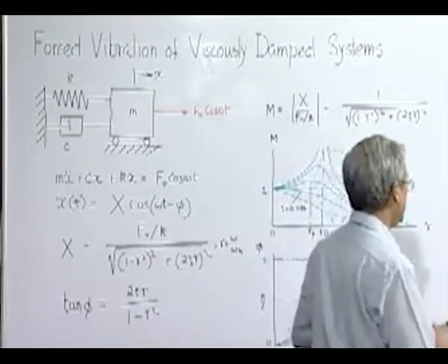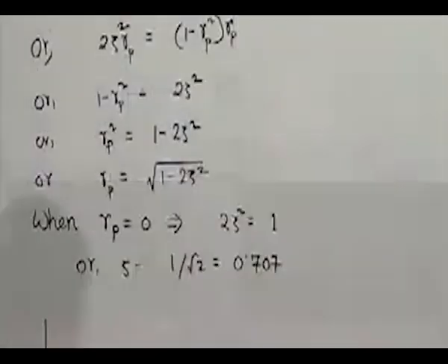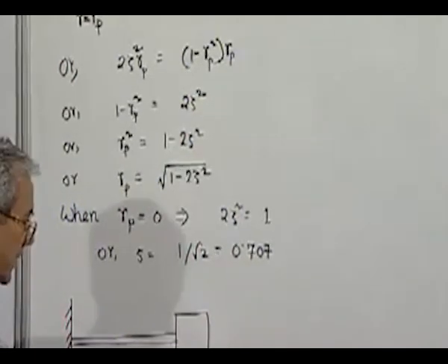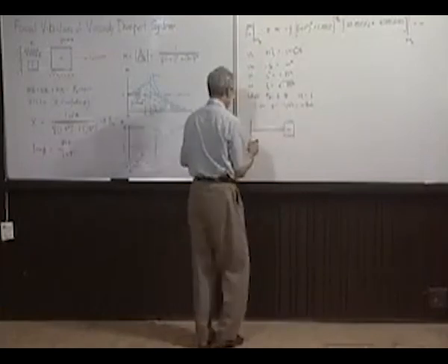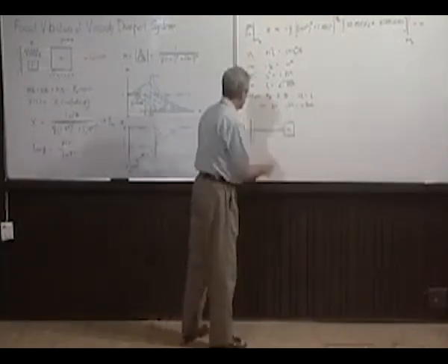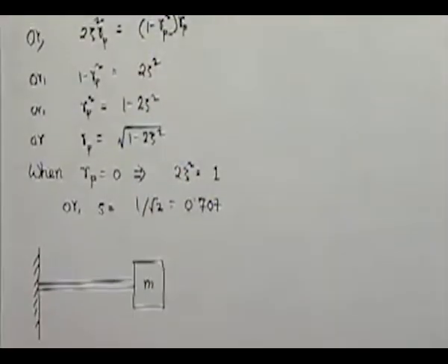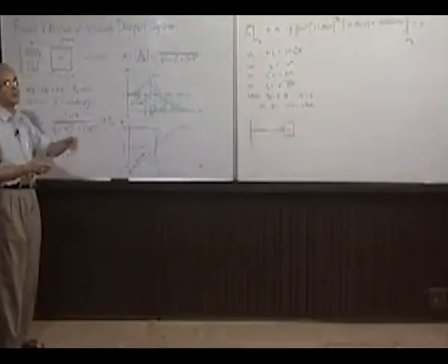That is, suppose there is a cantilever beam carrying some kind of a mass here. If a load is applied here statically, the stress which will be generated or strain which will be developed will be much less compared to the static situation if the same load is applied at a much higher frequency. So this is a very important observation, and we will see that this can be used in design